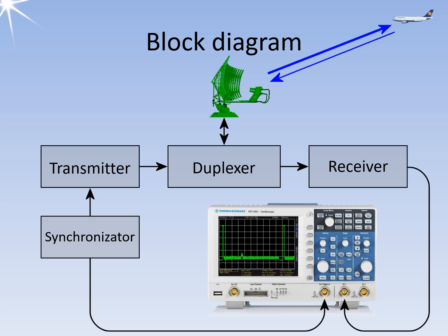The transmitting pulse also passes through the receiver circuits. Time delays in the internal circuits are compensated on the oscilloscope. The runtime is measured from the leading edge of the shown transmit pulse to the leading edge of the echo signal. Both pulses pass through the same circuits and thus always have the same internal delay time.